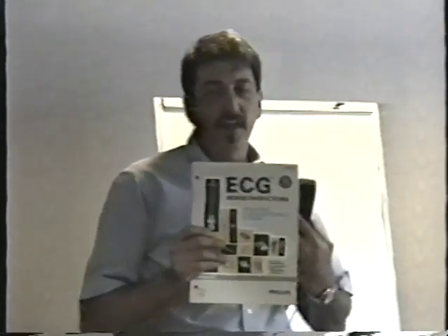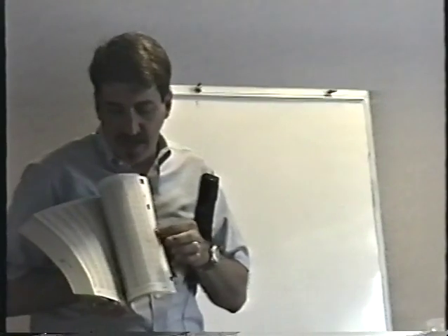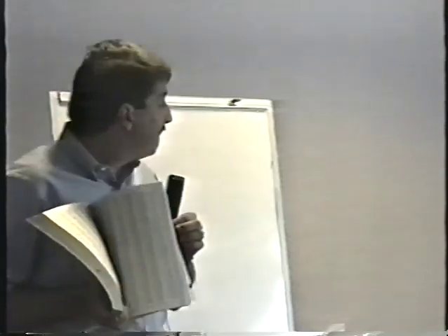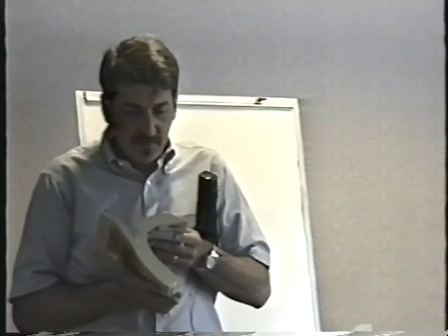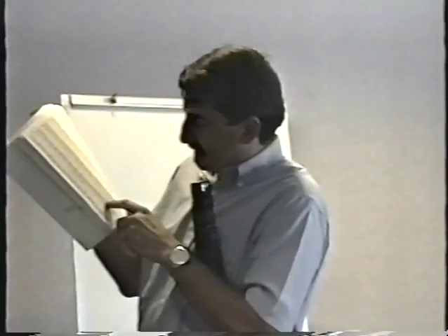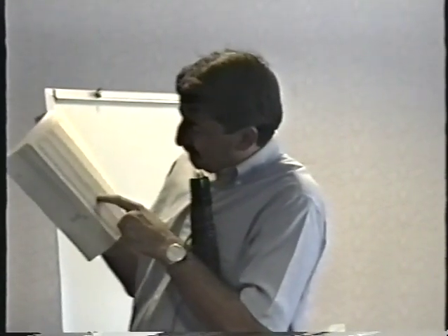So here's what this is. In the back of the book is a list of all transistors and integrated circuits and diodes known to human science, just about. There's just a lot of them back here, and it's in alphanumeric order. Let's say that we have a 2N3055 and it's bad. Let's look up 2N3055 in the back. It would be on page 2-28, in the second column over, the fifth paragraph up, 2N3055.